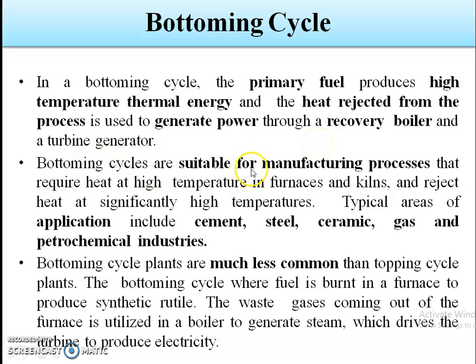Bottoming cycles are suitable for manufacturing processes that require heat at high temperature in a furnace, and then reject the heat at significantly high temperature. Application areas include the cement industry, steel industry, ceramic industries, and glass and petrochemical industries. Generally, in the bottoming cycle for glass, cement or steel industries, we need